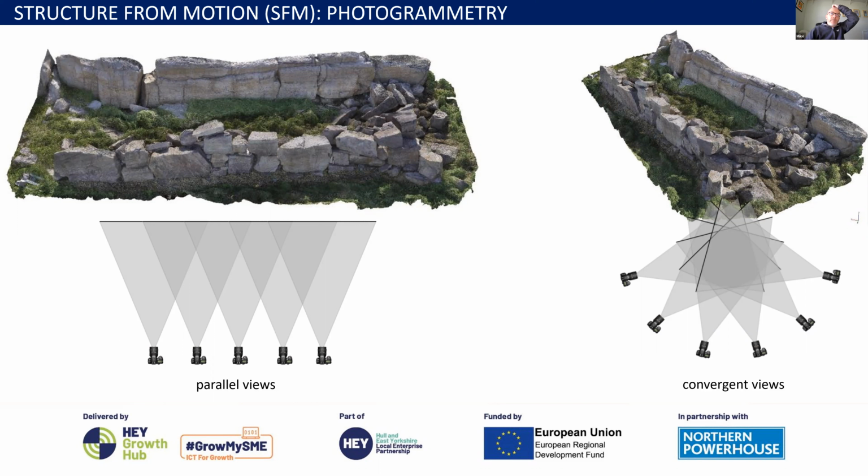We like this technique because it's very portable, unlike a terrestrial laser scanner that is not so portable. But the only downside with this is that you take the photos, you then have to take them back to a lab or to your laptop to upload them and to process them. And the software at the moment, the better software for this technique, is expensive, quite time consuming, and complex, but it does produce a good result to create a three-dimensional model. But it's a tool that we use. It complements terrestrial laser scanning very well, and you can take these aerial views if you strap a good digital SLR to a drone.